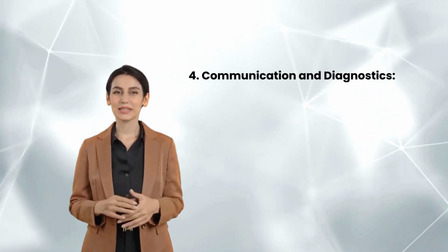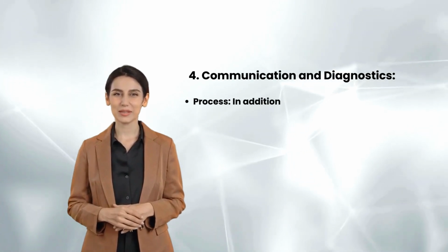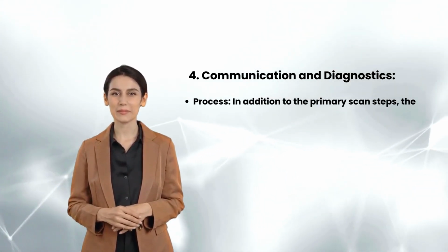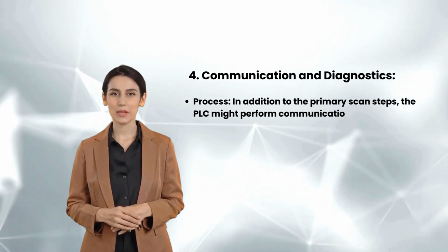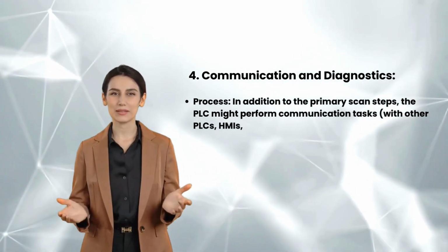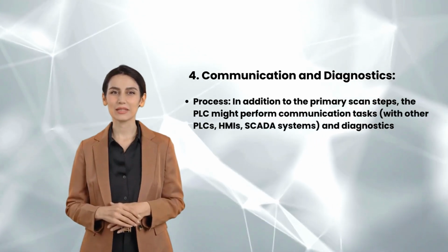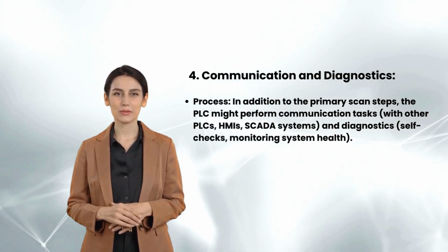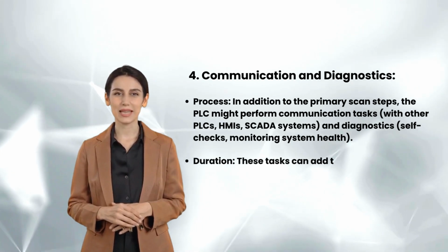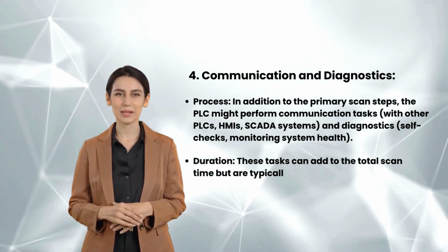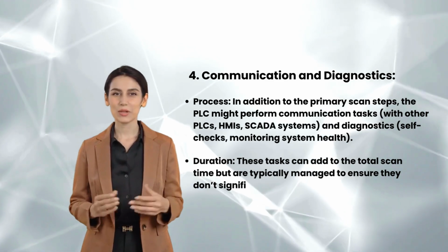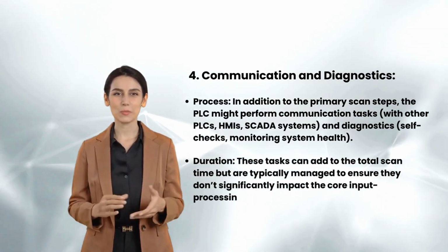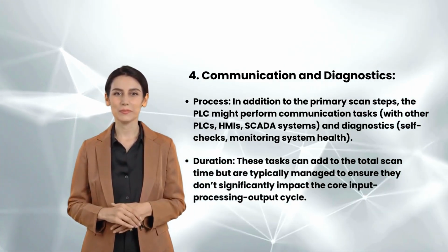4. Communication and diagnostics. Process. In addition to the primary scan steps, the PLC might perform communication tasks with other PLCs, HMIs, SCADA systems, and diagnostics, self-checks, monitoring system health. Duration. These tasks can add to the total scan time but are typically managed to ensure they don't significantly impact the core input processing output cycle.